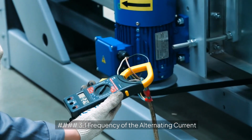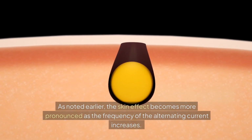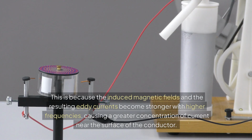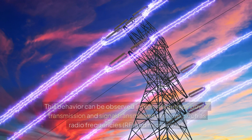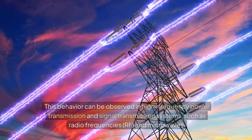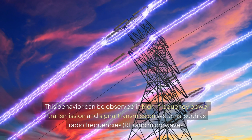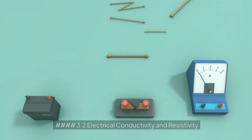Number 3.1 Frequency of the alternating current. As noted earlier, the skin effect becomes more pronounced as the frequency of the alternating current increases. This is because the induced magnetic fields and the resulting eddy currents become stronger with higher frequencies, causing a greater concentration of current near the surface of the conductor. This behavior can be observed in high-frequency power transmission and signal transmission systems, such as radio frequencies, RF, and microwaves.